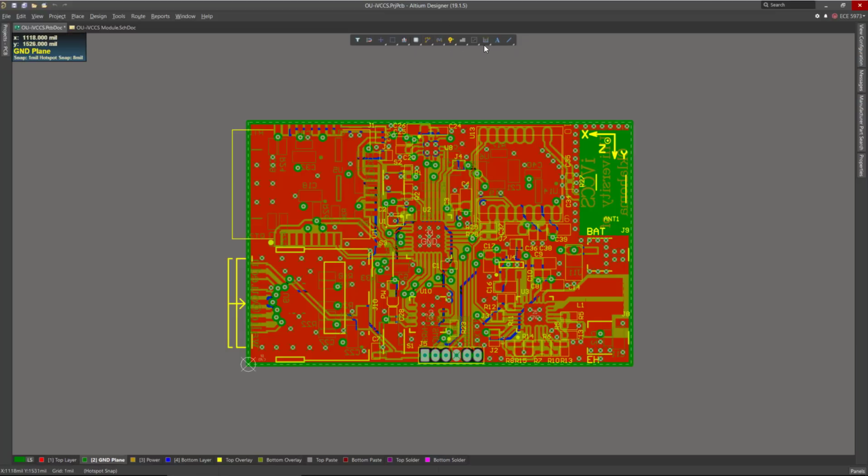Same thing in here. Let's see, for instance, this one. This is for the dimensions. The default one is the last one you selected. If you select standard dimensions, you can use escape to release it, or right click as we said. So if we select this one, right click, it will release, or you can press escape, it will also release. So you will see only the last command you selected. Let's select a different one, baseline dimension. So it's the default right now. It will keep the last command you selected.